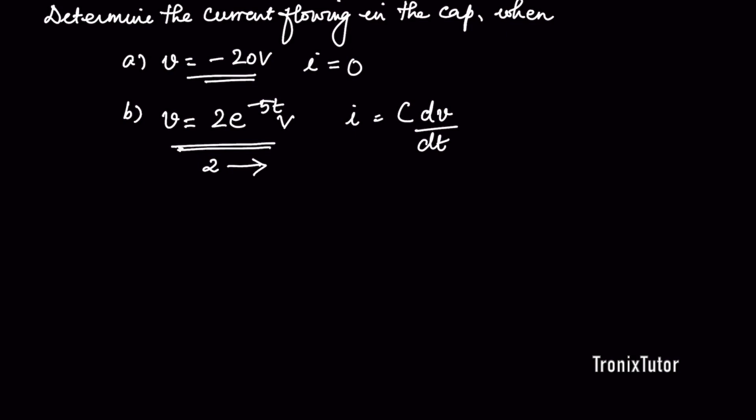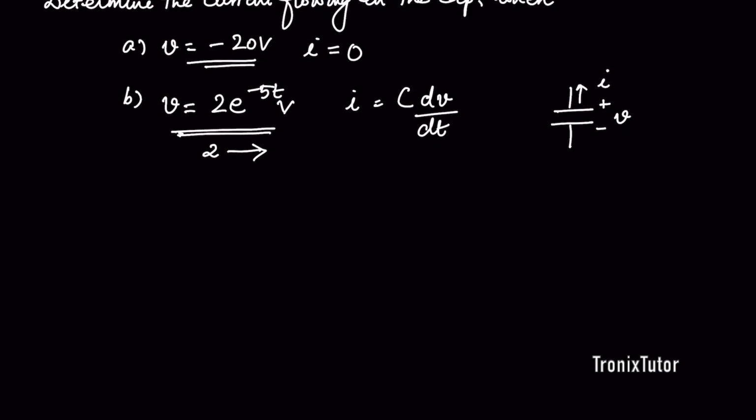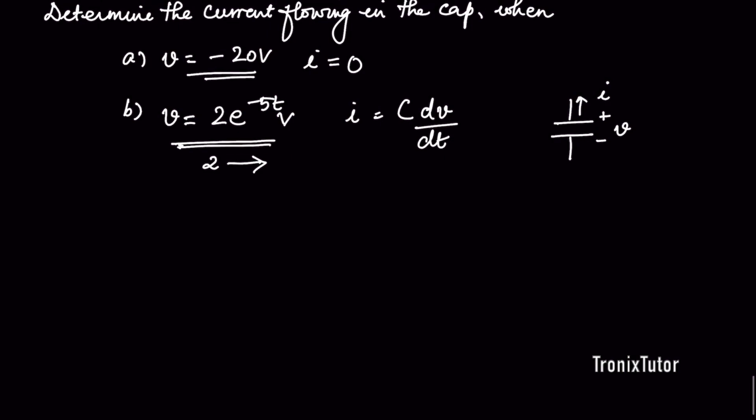Therefore, if you now look at this capacitor, we expect that the current in this capacitor is actually going to flow out of the capacitor. So in our convention, we expect that the current that is going to be calculated is going to be a negative value, or in other words, the capacitor is discharging, right? And that's going to flow out directly from the derivative.